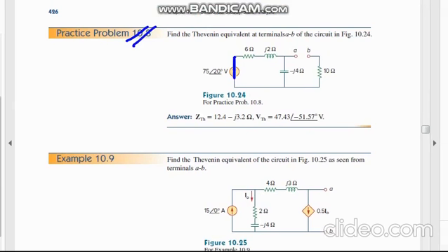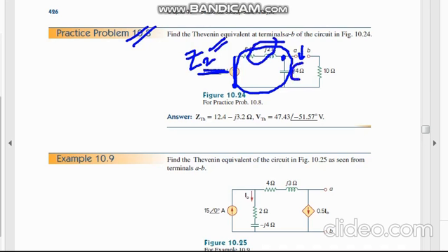So now, looking back at that source, just the practice problem: find the Thevenin voltage. First of all, short this voltage source, then find out the Z Thevenin by looking from here. If it is shorted out, this is the parallel port, and first of all find out the Z2, which will be the parallel of these two, the 6 ohm plus J2 ohm and the minus J4 ohm.